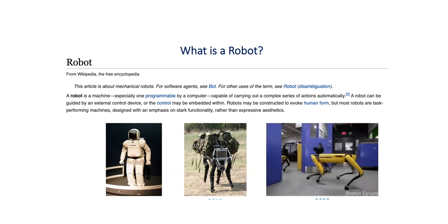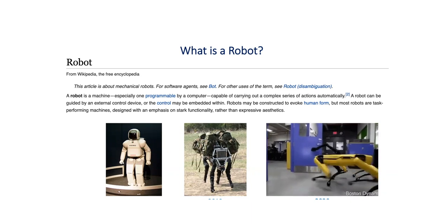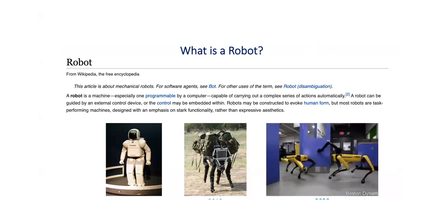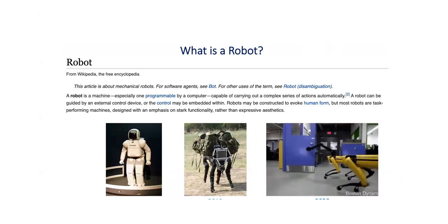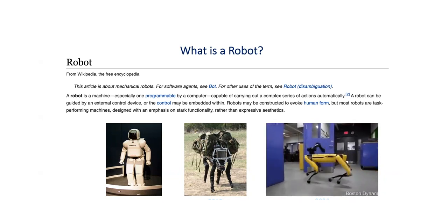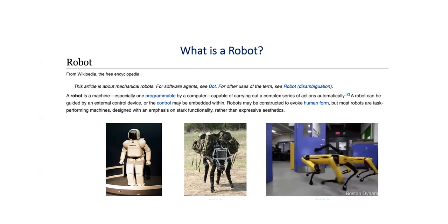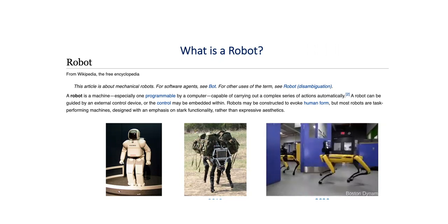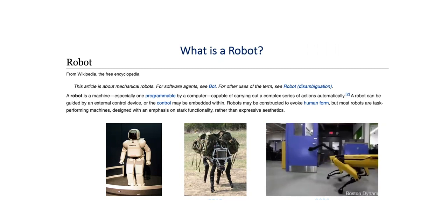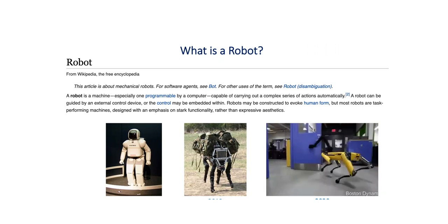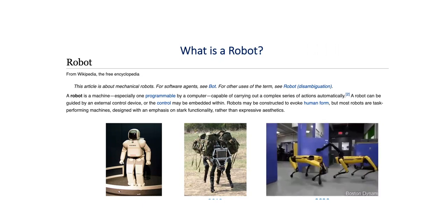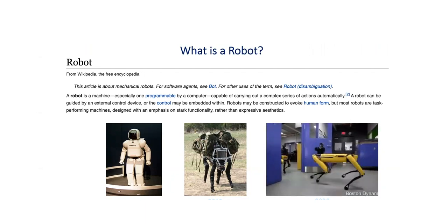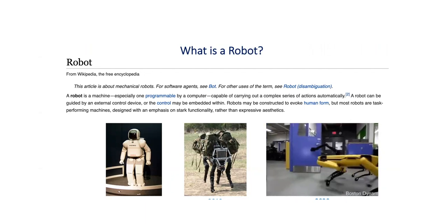So if you have a room in an aseptic condition, in ATEX condition, you cannot interact with everything that has been validated. But these robots, once they have been aseptically accepted, are not interacting physically with the already validated systems, with the validated assets, and these robots can be plugged with cameras, infrared sensors, thermosensors, sound sensors, vision, AI vision, in order to recognize wrong behaviors or procedures. They can be plugged with this kind of modern sensors without interacting physically with the validated systems.